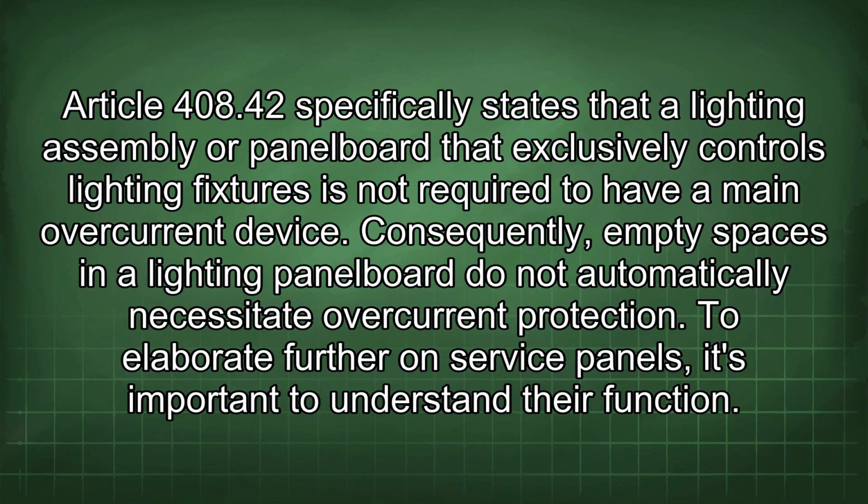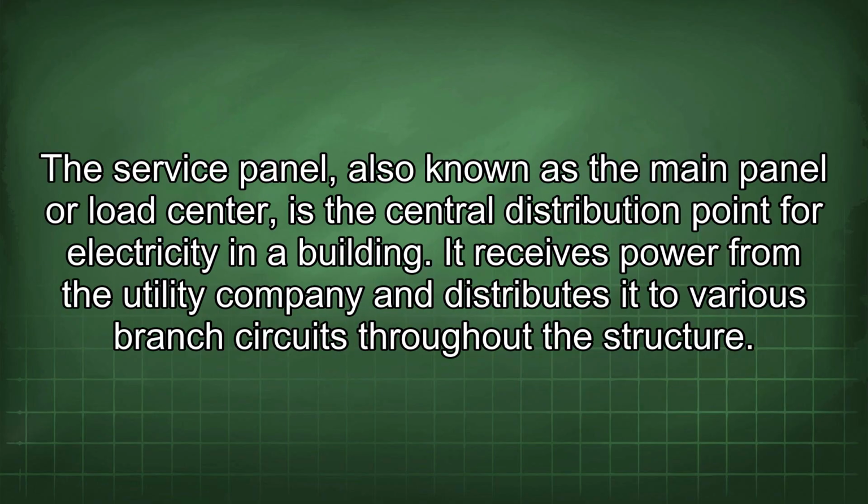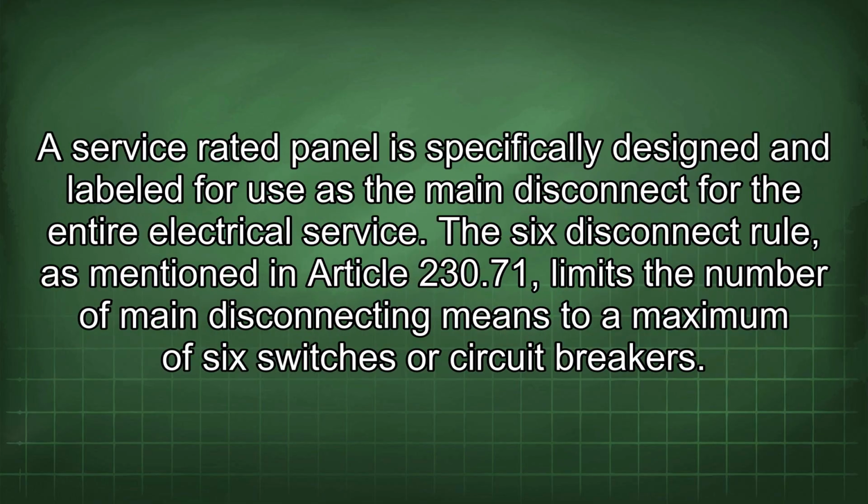To elaborate further on service panels, it's important to understand their function. The service panel, also known as the main panel or load center, is the central distribution point for electricity in a building. It receives power from the utility company and distributes it to various branch circuits throughout the structure. A service-rated panel is specifically designed and labeled for use as the main disconnect for the entire electrical service.